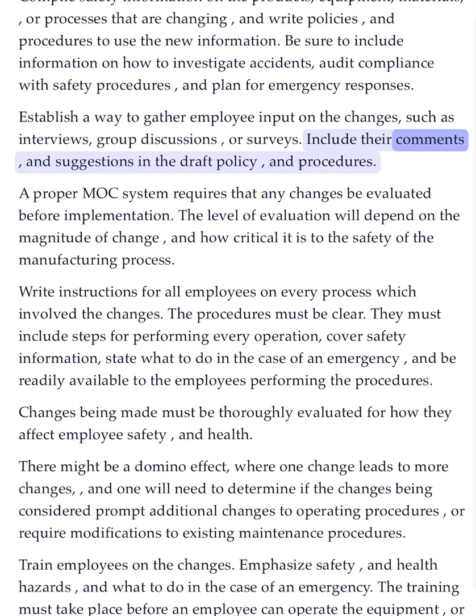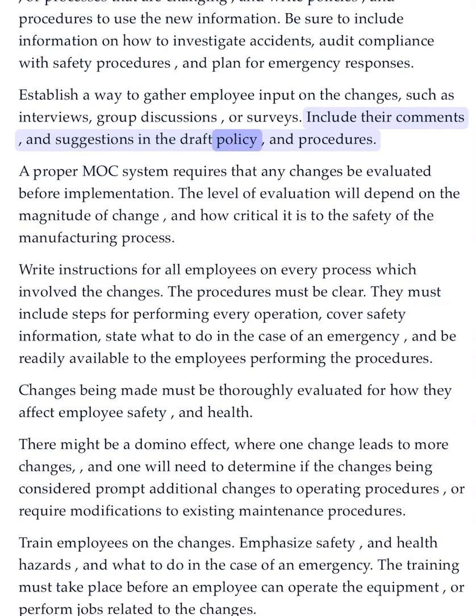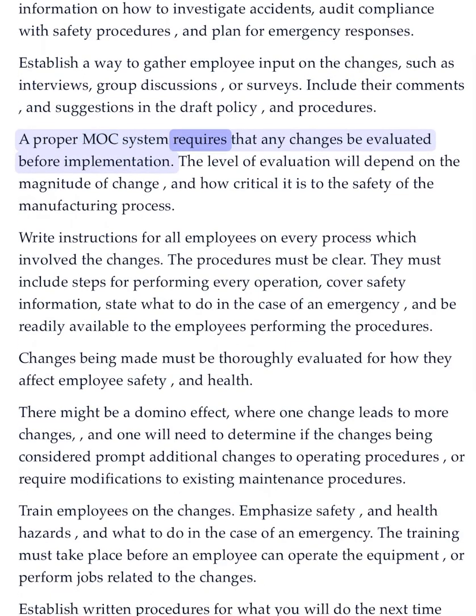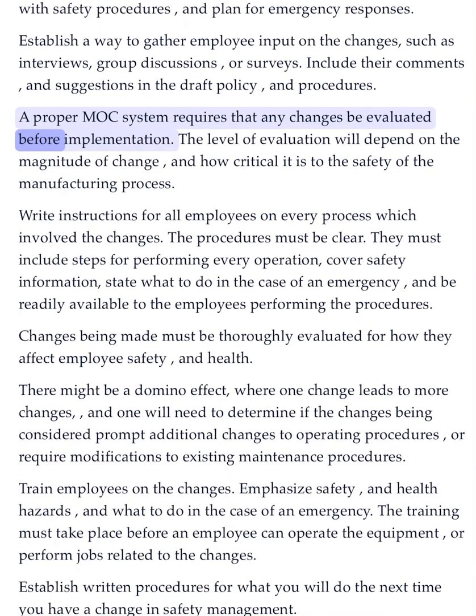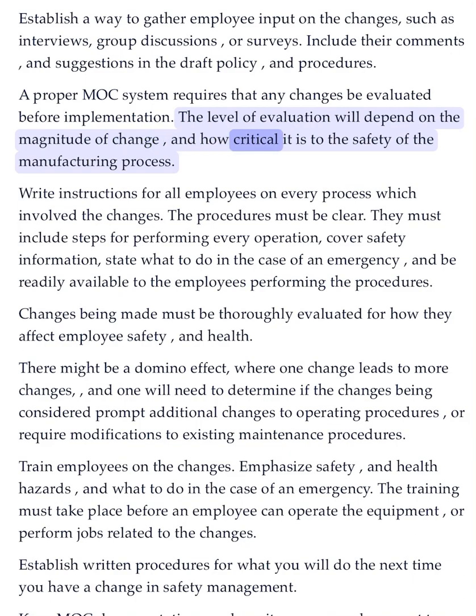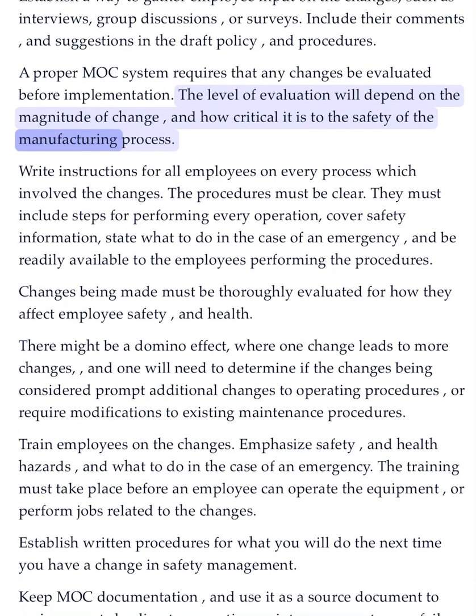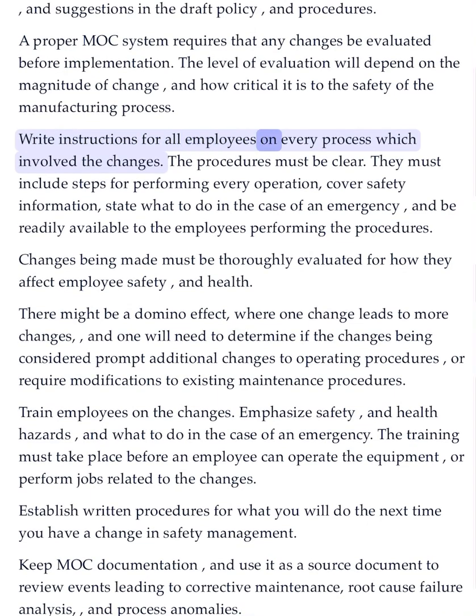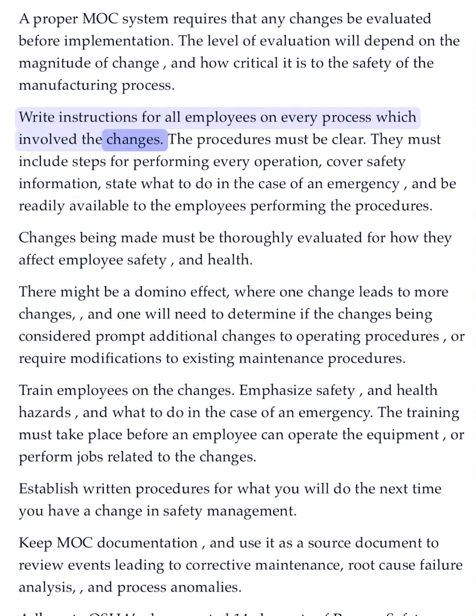Include their comments and suggestions in the draft policy and procedures. A proper MOC system requires that any changes be evaluated before implementation. The level of evaluation will depend on the magnitude of change, and how critical it is to the safety of the manufacturing process. Write instructions for all employees on every process which involved the changes.